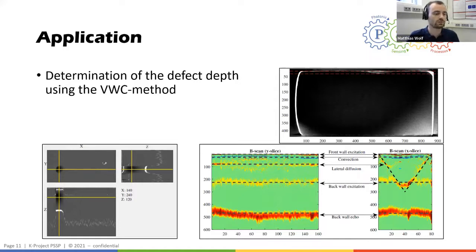We were also able to look at the region where one of the defects occurred, that is shown on the left-hand side of the slide, where you can clearly see also a reconstructed interface where the defect is located. And this information could also be used to estimate the approximate depth of the defect. Just for comparison, on the top right side of this slide, you can see a cross-section of that defect, and this figure was generated using computed tomography.